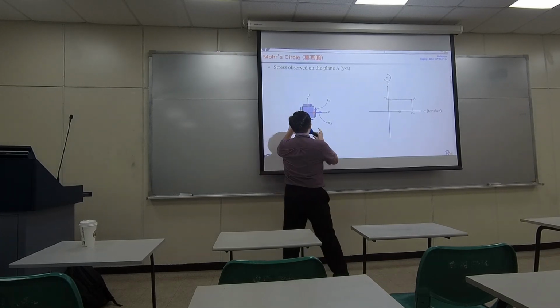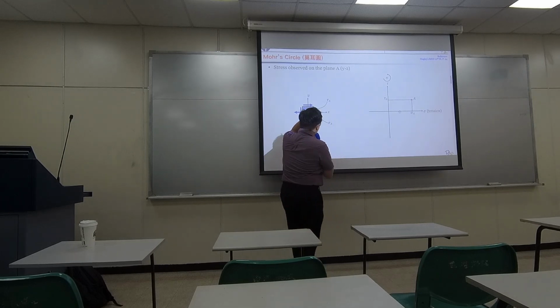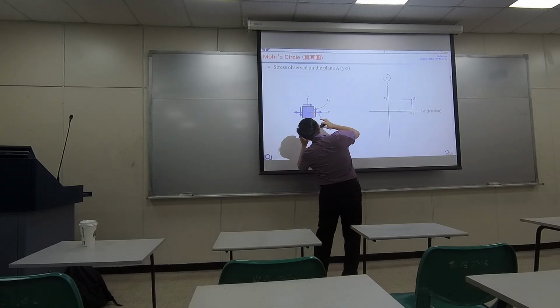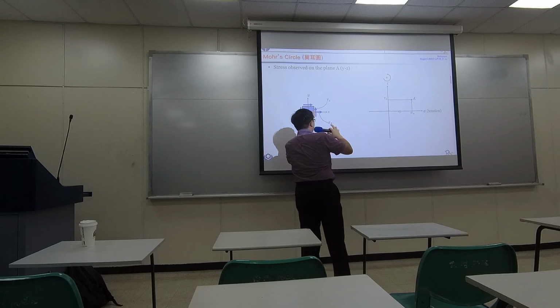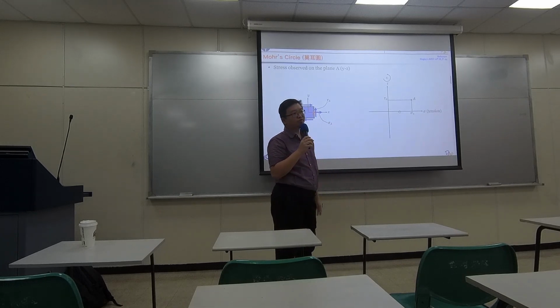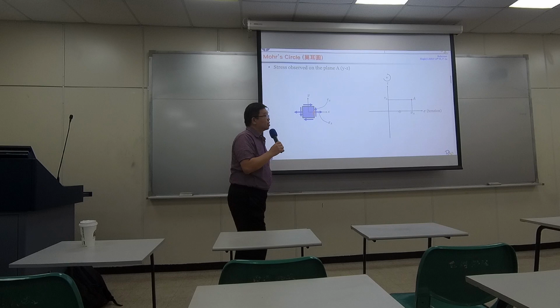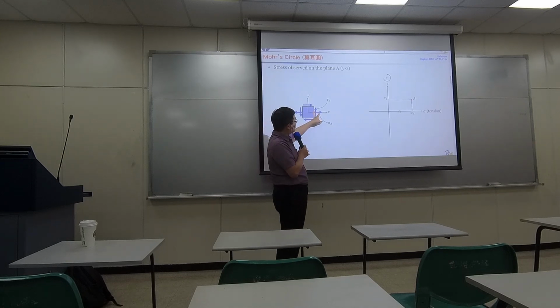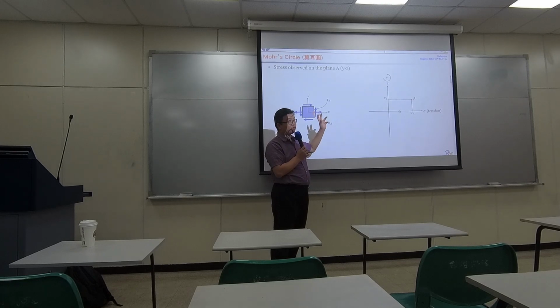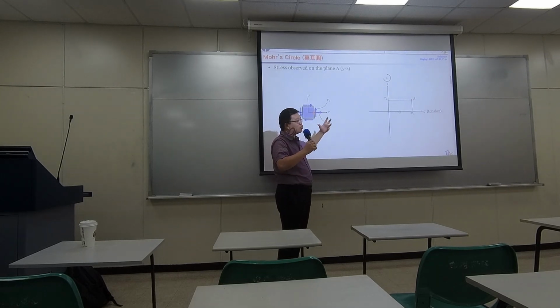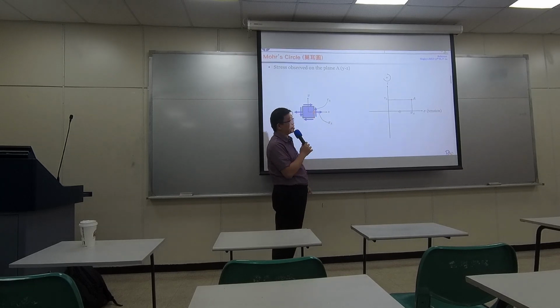So we just want to change how we observe it, and eventually we will find a new orientation, and we will see the so-called principal coordinate, principal axis. On the principal axis, we have the largest normal stress. So if we only use the original normal stress to design our material, that is actually not the largest stress being applied to the material.